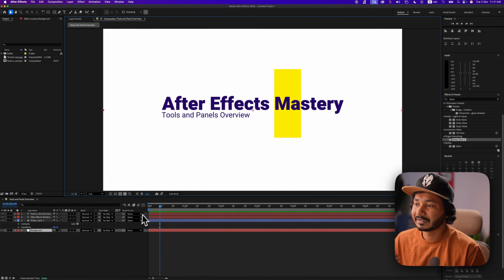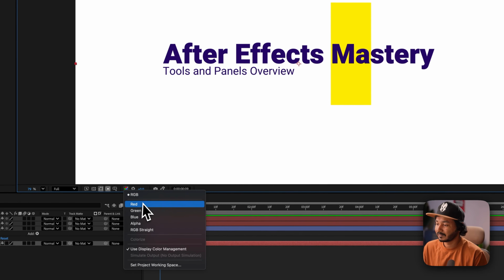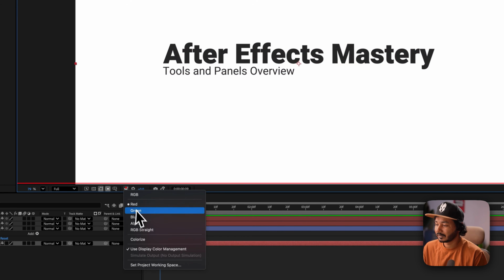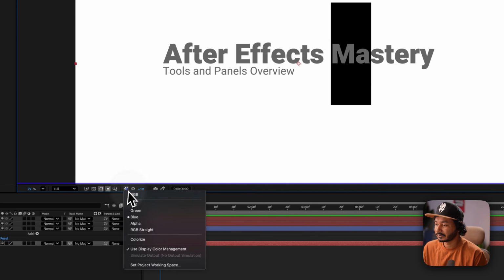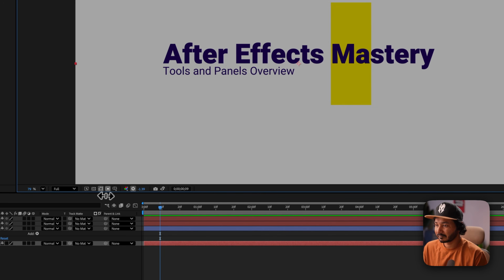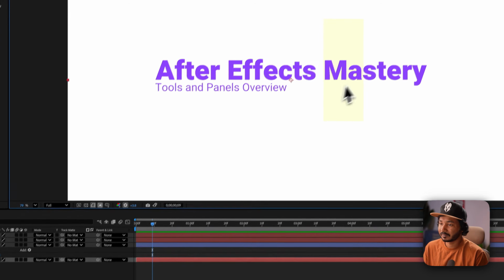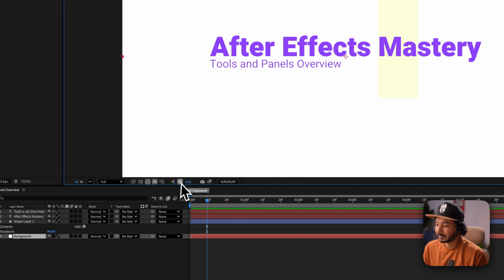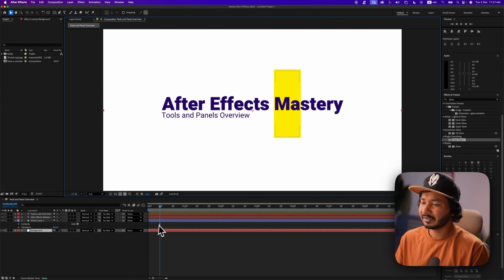Now if you want to see the channels, you can click here, then you can see the red channel, you can see the blue channel. You can just select it and it will show the channel separately. I will select RGB, and from here you can change the exposure of your composition preview. You can decrease it or increase it, and to reset it you can just click on this icon, reset exposure. It will reset the exposure.